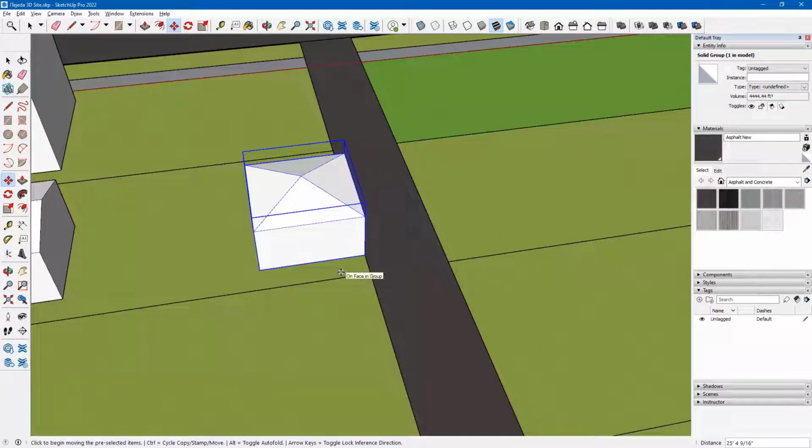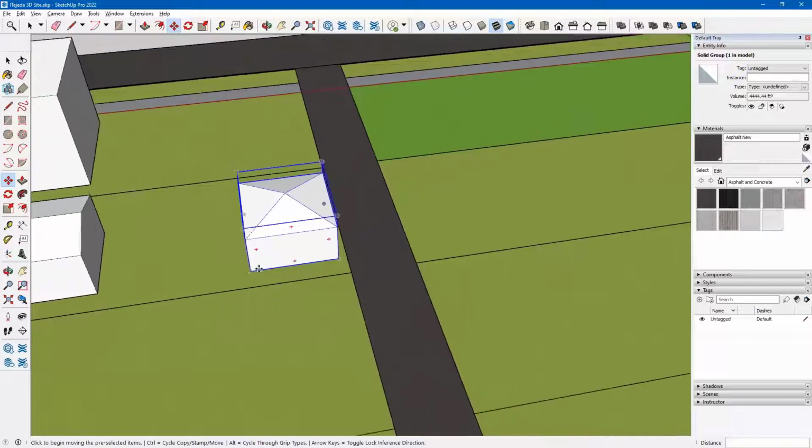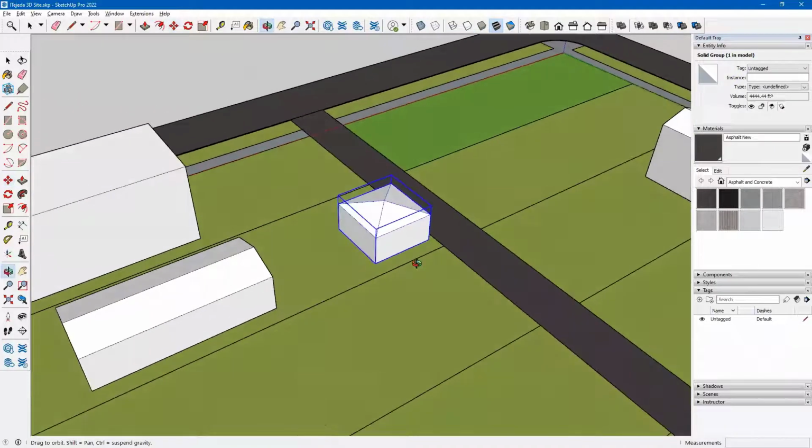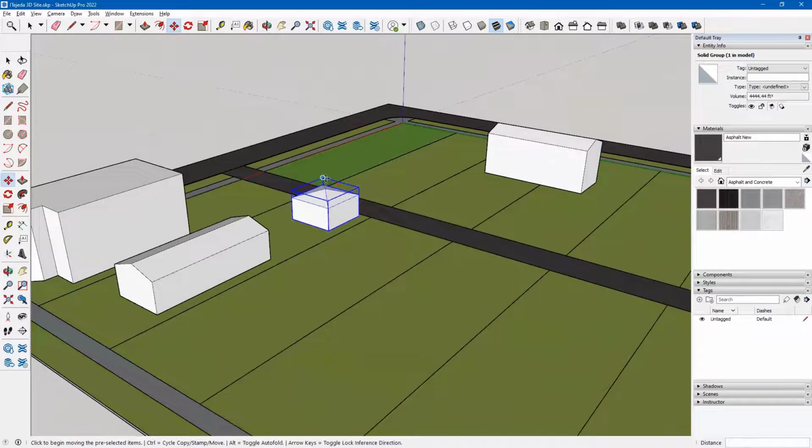Now, the garage doesn't exactly sit on the alley like that. It's usually in about a foot or even 2 feet. So now I'm just going to take it and click on this corner and bring it in, and I'll type in 2 feet, enter. So that's in a position where I believe it's going to be okay. And now I have one more building to move. I'll use my space bar, select this building, and I can either move it and then rotate or rotate and then move.